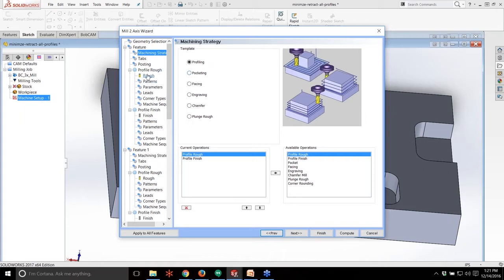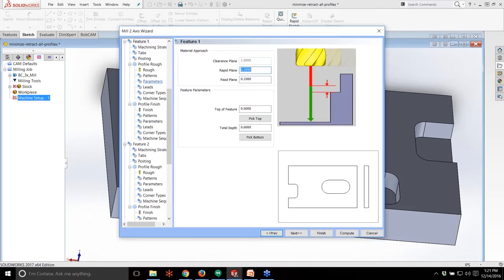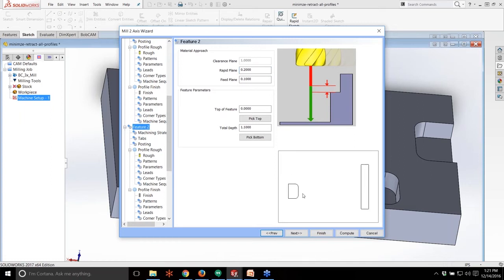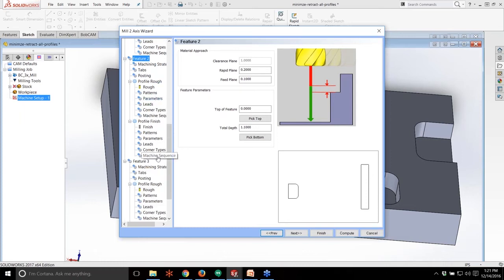The other nice side is you guys go down here to the actual next one. So let's say we go to feature 1. That is this profile shape. Okay, awesome. We can go in and customize that as well, cutting out the outer profile and in between here. Okay, and then you go down to feature 2. Okay, this is this slot here, that's fine as well. We can use profile on that. And then the last feature is going to be the pocket.